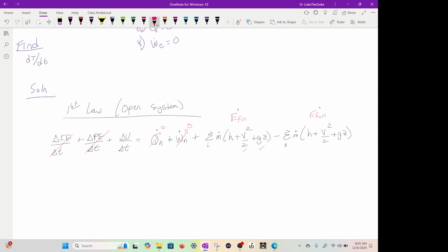In the energy of the fluid, you could have kinetic, which is this one, potential, and what they call enthalpy, which is internal energy plus pressure energy. Internal energy, U, relates to temperature. So something will have energy based on its temperature. And then this is pressure energy. Think of it like an air compressor. You pressurize the air, it now has stored energy, and when you open the valve, that energy is released to kinetic. You can think of a squirt gun the same way.